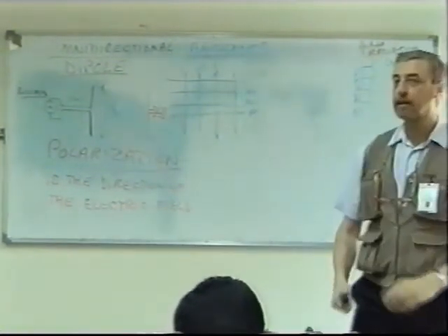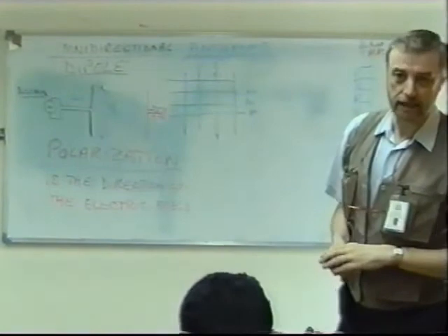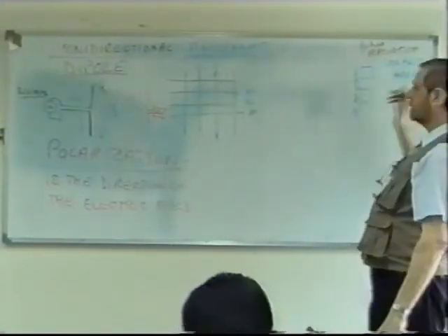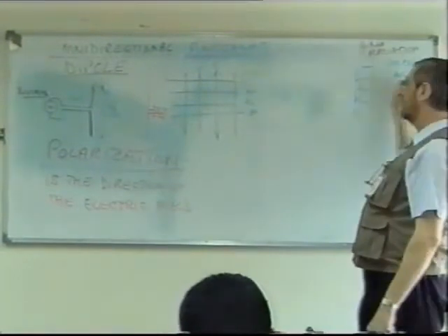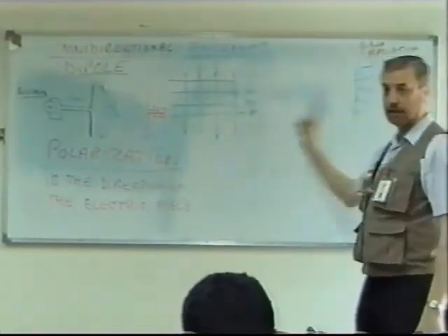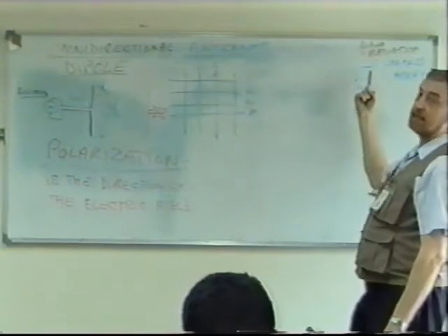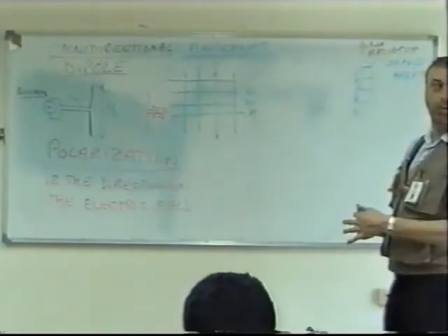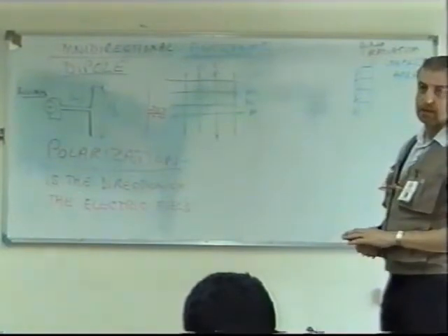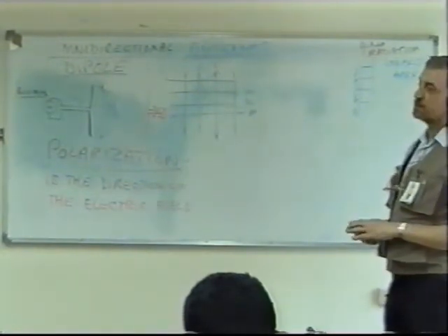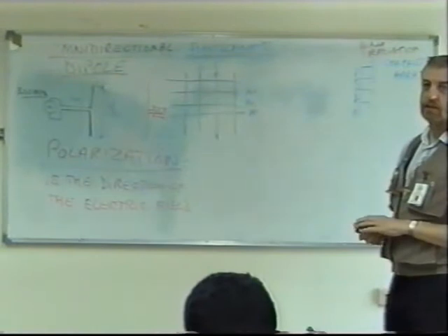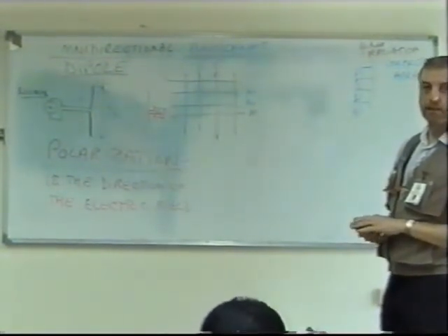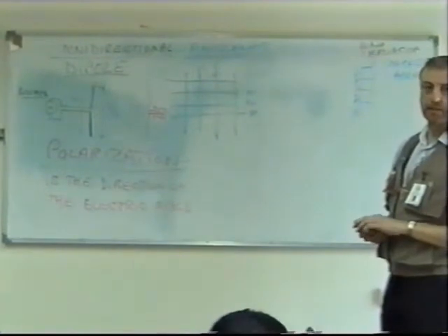We call that it is directional. It is directional, yes. It is an example of a directional antenna. But it's only directional in the sense that it's all the way around 360 degrees, but the radiation up, and indeed the radiation down to the ground, is minimum. So we don't waste power. To answer your question exactly how it works, it really is quite complex. Directional for all sides except up and down, yes.